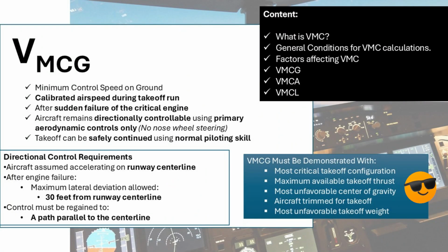VMCG must be established under specific certification conditions. These include the most critical takeoff configuration, maximum available takeoff thrust, the most unfavorable center of gravity, the aircraft trimmed for takeoff, and the most unfavorable takeoff weight.